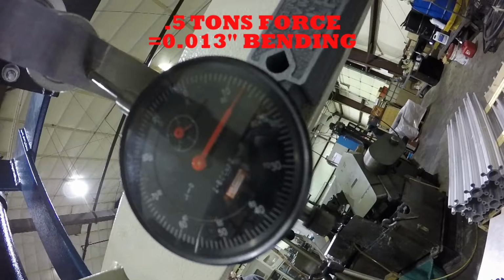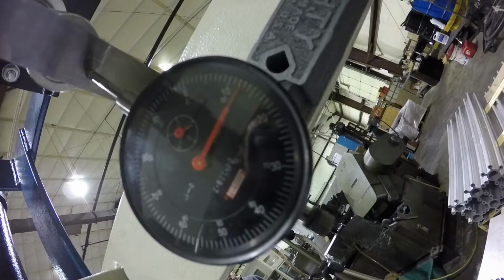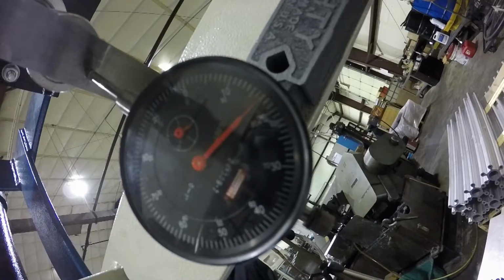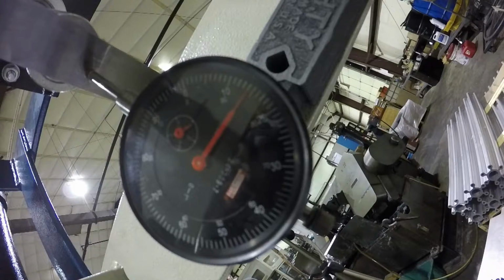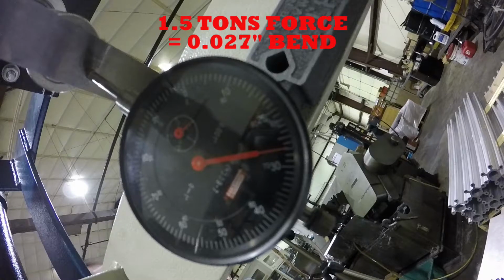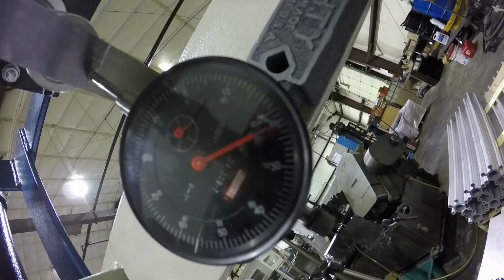Here you can see that 1/2 ton equals 13 thousandths of an inch bend. After recording our results, we then proceeded to add more force to the beam. Here you can see that 1 ton equals 17 thousandths of an inch bend. We then repeated the process and recorded our results in increments of 1.5 tons, 2 tons, and 2.5 tons.